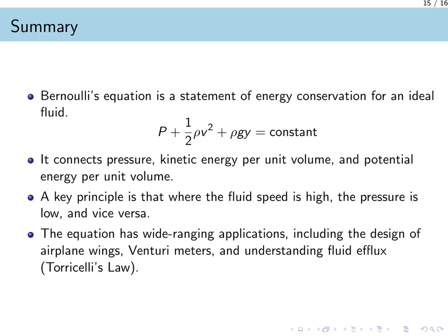Each term has a physical meaning. P is the static pressure. The term 1/2 ρv² represents the kinetic energy per unit volume. The term ρgy represents the potential energy per unit volume.